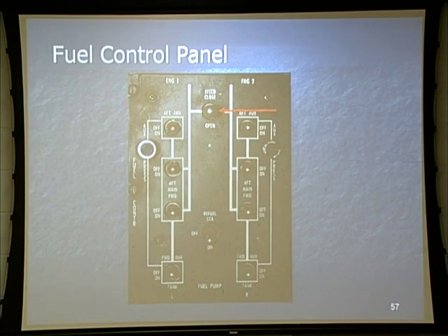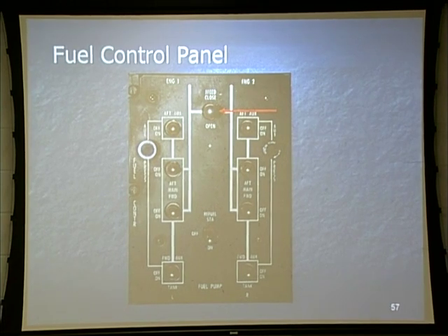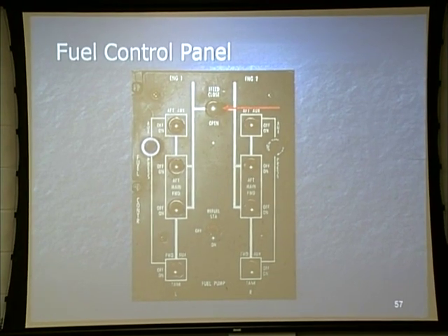In order to dictate which way that fuel process goes, it's based on whatever tank has low pressure. That's what's going to happen. Okay, whether you turned off the pumps or whether the pumps weren't working, what's going to dictate which way it goes is it's going to go high pressure to low pressure. That's the way it's going to go.